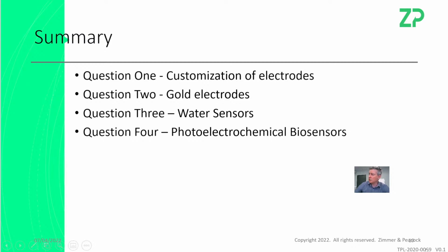Be very careful. In terms of water sensors, I think a good place to start is don't start with half a dozen sensors. I'd start with the pH sensor and the nitrate sensor. These are our most robust sensors. I didn't say it, but we've probably spent easily over £1 million UK pounds on that nitrate sensor, and I think it's fair to say we've easily spent over £500,000 so far on the pH sensors. So those are the two that are most robust.